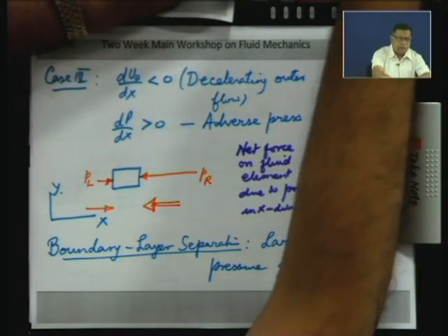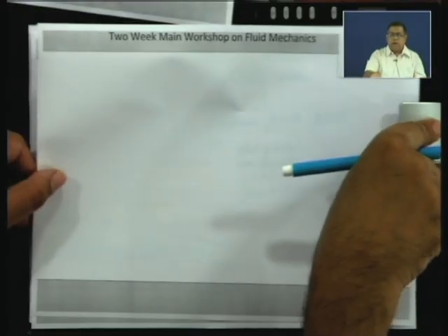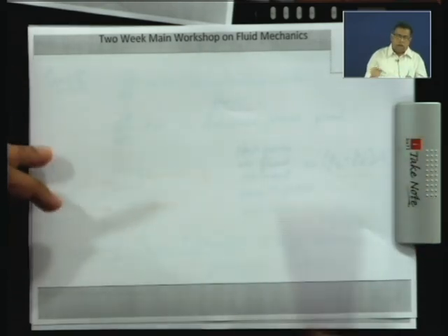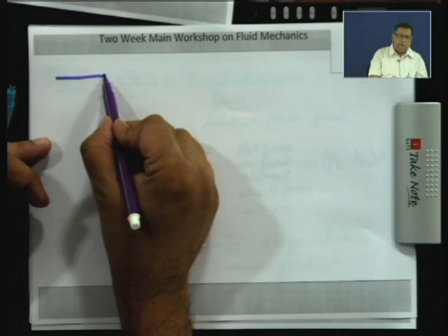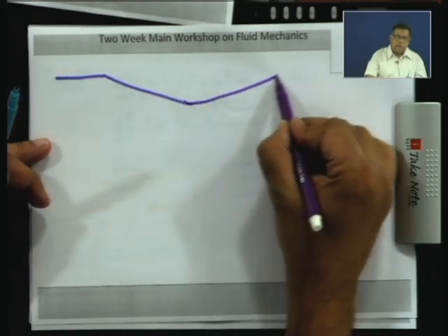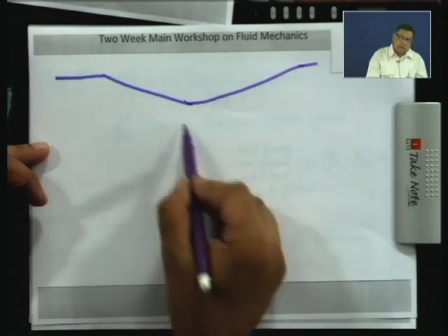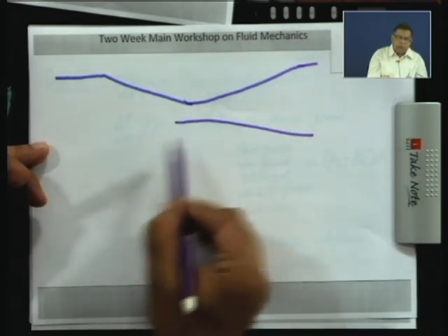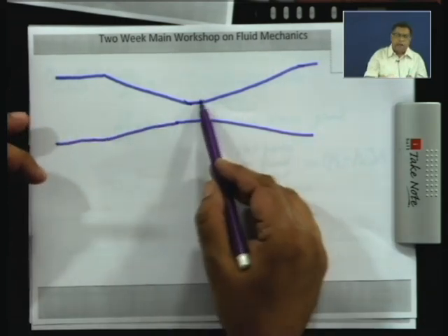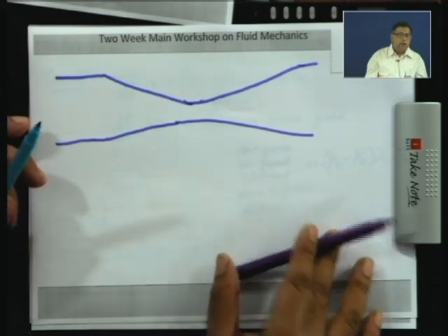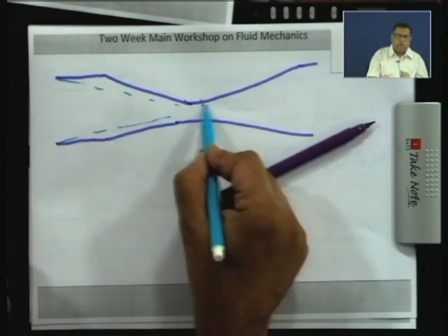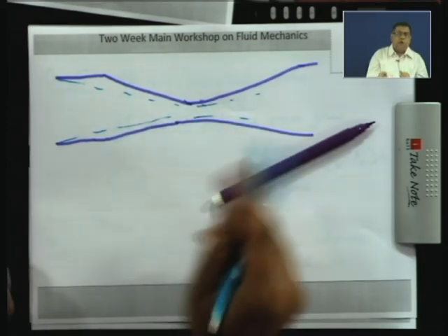Now, I will come back and answer one question which was asked before when I talked about the Venturi meter. So, that was a converging diverging duct. So, that was an internal flow, but even in internal flows you may have boundary layers. So, the question which was asked 3 times to me is, why is the angle of divergence less over here? Now, here what will happen is, you will have boundary layers growing on both the walls, and what we were calling the outward flow.